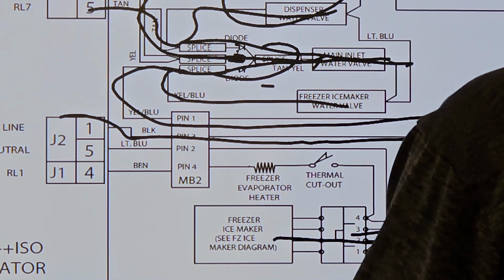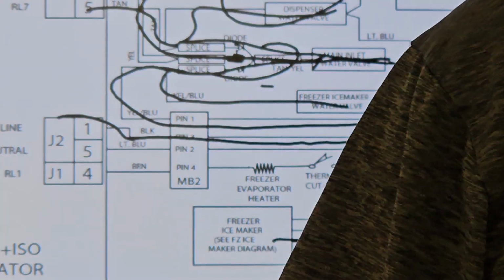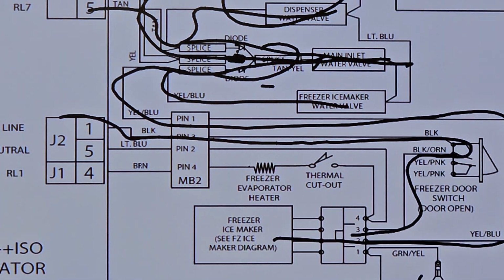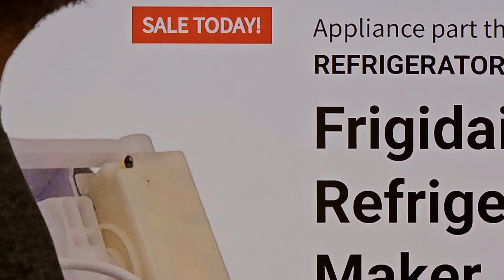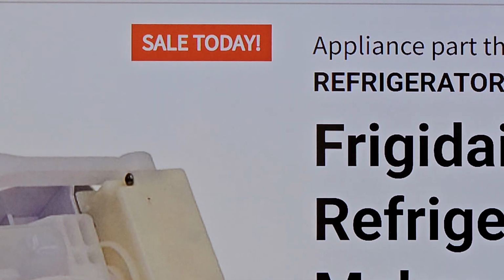Can you repeat this? If you go to someone's machine, the flex tray, and you see ice in the tray, you go into diagnostics and you say, drop the ice. Would it be the tray sensor? Most likely the tray sensor is bad. Very good. The tray sensor here is possibly the problem because it's not sensing the temperature and telling the board, hey, drop the ice.